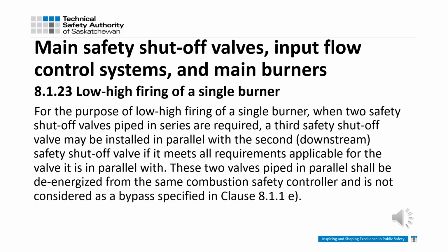8.1.23 Low, high firing of a single burner. This clause gives you the requirements for having a third safety shutoff valve in parallel with the second and downstream of the first. The two valves piped in parallel shall be de-energized from the same combustion safety controller and is not considered a bypass as per 8.1.1e.